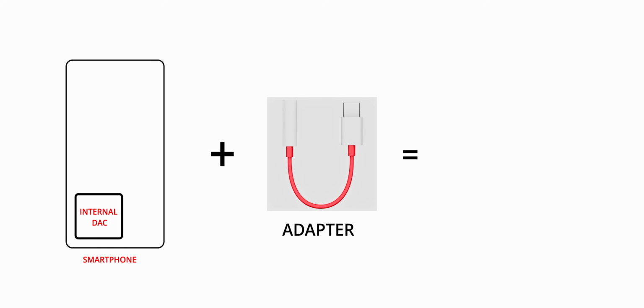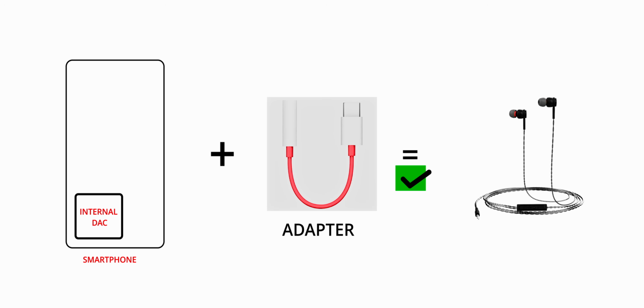But when smartphone companies began to remove that 3.5mm jack, they had to add another functionality to this port, which is providing analog signals through this port, for which the internal DACs of your smartphones will be used. It was just rerouting the signals from the 3.5mm jack, which was not there, back to the Type-C port so that people could use their existing earphones or headphones with a 3.5mm jack, and you will be able to make this connection via some kind of a Type-C adapter.